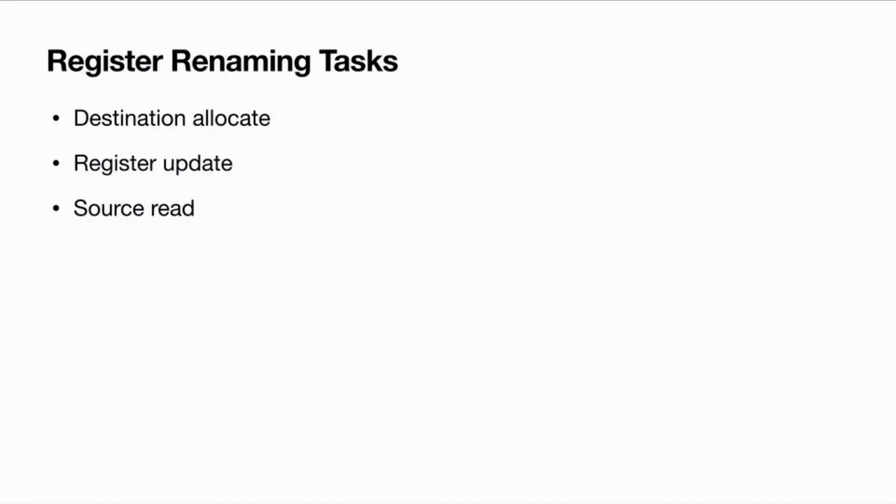When a function unit adder finishes its execution, in which location are we going to write the data? R1 or T1? It should be R1, right? Yeah, but this is because I said instruction finishes execution, not completed.